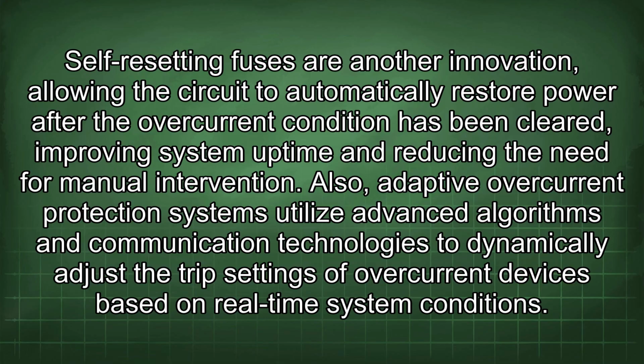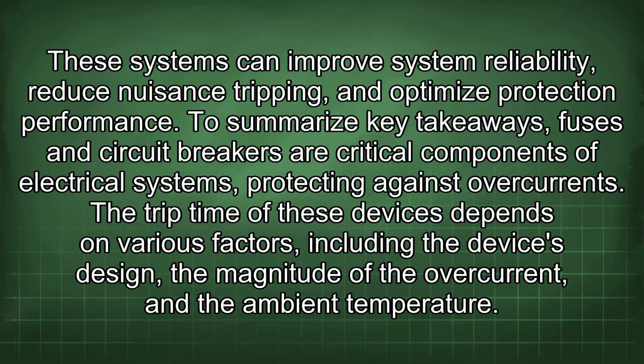Also, adaptive overcurrent protection systems utilize advanced algorithms and communication technologies to dynamically adjust the trip settings of overcurrent devices based on real-time system conditions. These systems can improve system reliability, reduce nuisance tripping, and optimize protection performance.